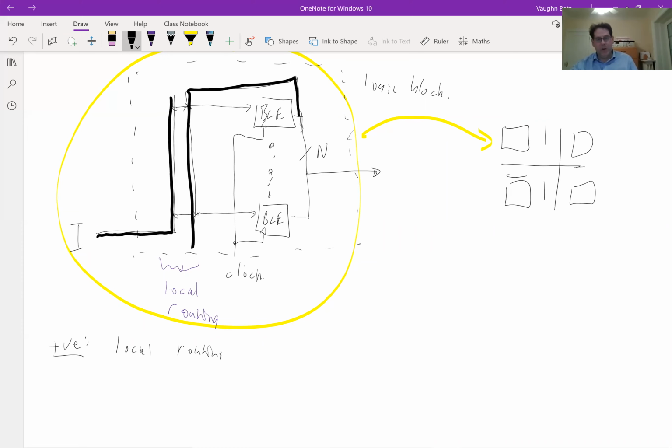You may connect that to other routing wires with programmable switches. You have another programmable switch to connect to an input of a logic block. It's somewhat slower, even for very local connections, than this local routing, which can be done with just a single multiplexer from input to output. So the local routing is fast, so long as I don't make the clusters too big. So local routing is fast for small to medium clusters.